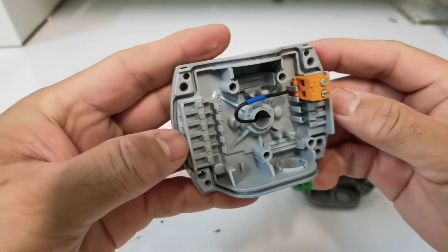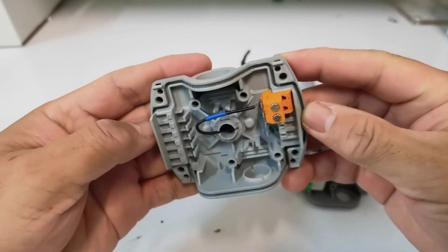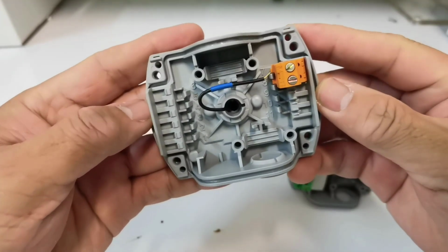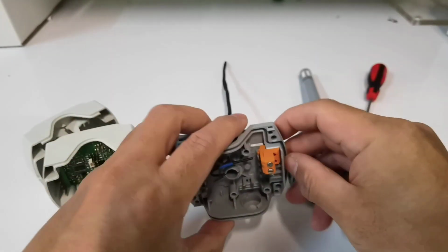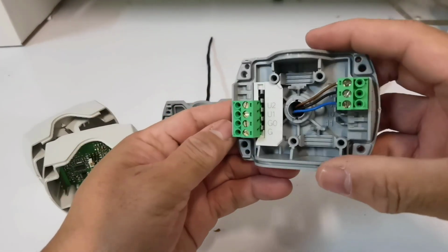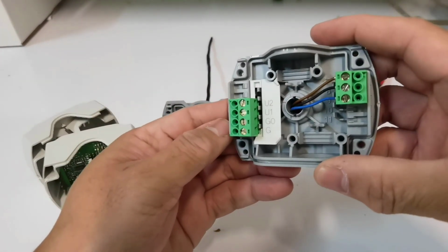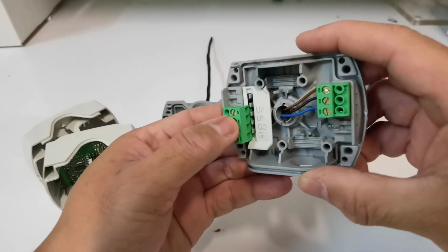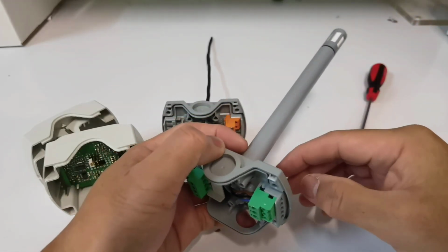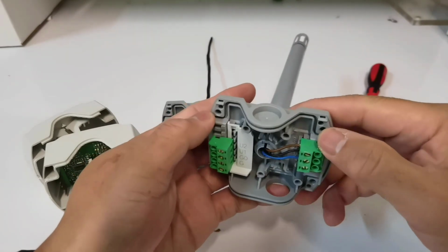The sensing element of the QAM is connected to a 2-port terminal block, and the QFM sensing element has a 3-port terminal block and another 4-port terminal block on the bottom left side, marked as U1, U2, G0, and G. Which one do you believe to be the active and which the passive sensor, then?